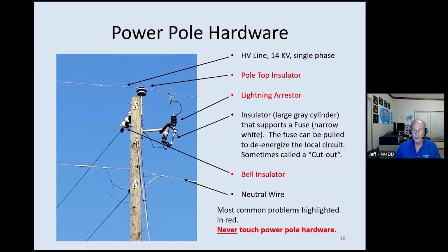Usually the person I'm talking to will know who his power company is. He'll turn in a trouble ticket, and I send him a report when I do an RFI assist. And that report has basically all the things we're talking about tonight. I'm going to send him a map showing where the noise is. I'm going to send him a drill down map showing which pole it is. I'm going to send him a picture of the pole. I'm going to have the part on the pole circled that is generating the noise.